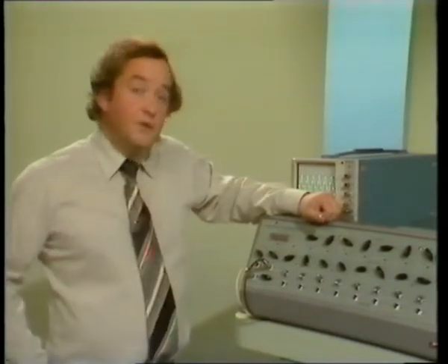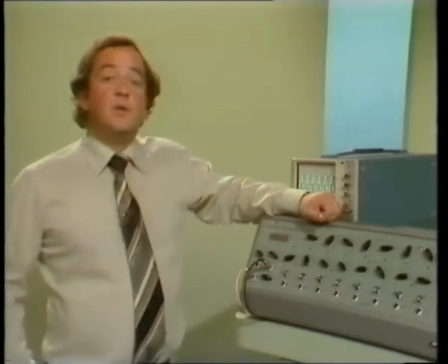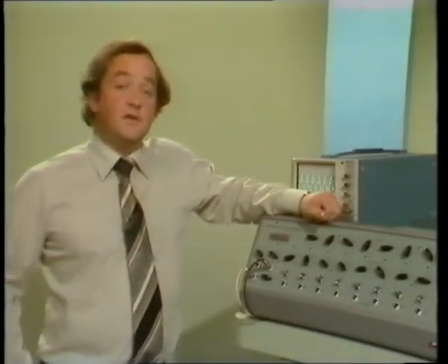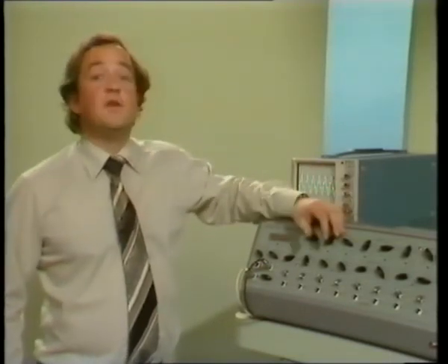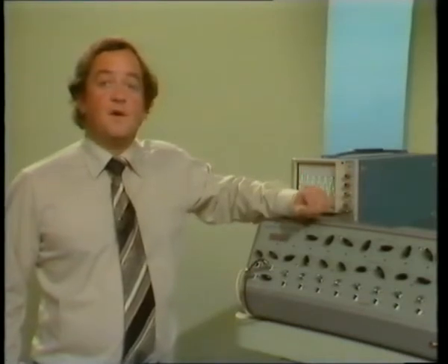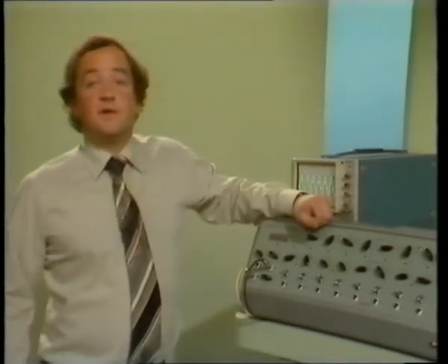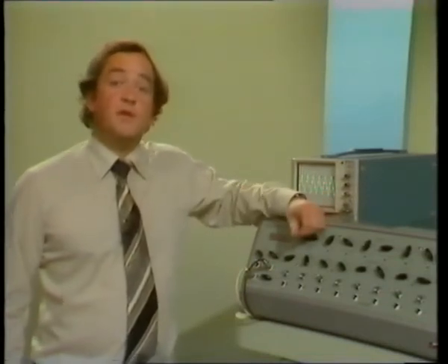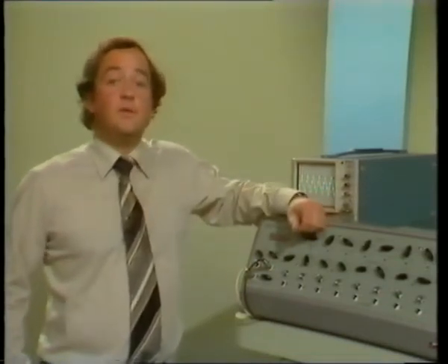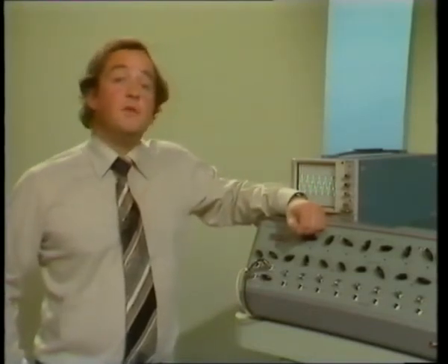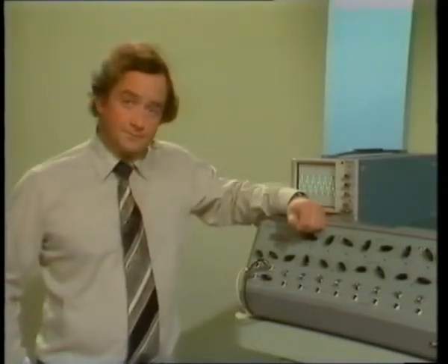Right, having looked at the speech signal in the frequency domain, we should now be in a position to specify the bandwidth of a system which has to handle speech. Mike showed us that the frequencies of the unvoiced sounds go way up above 5 kilohertz. So to transmit good quality speech, like you're receiving at the moment, the system has to cater for all these higher frequencies. But we don't necessarily need such a wide bandwidth to retain the intelligibility of speech.